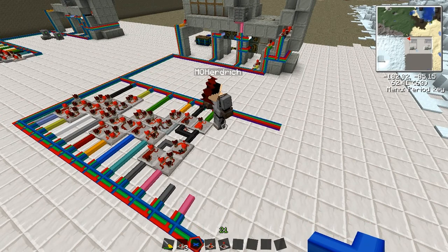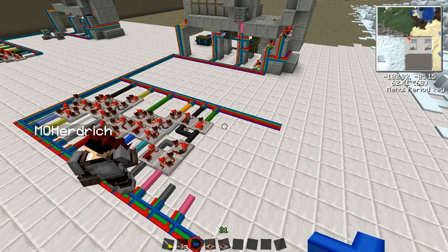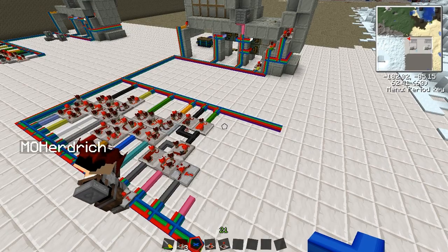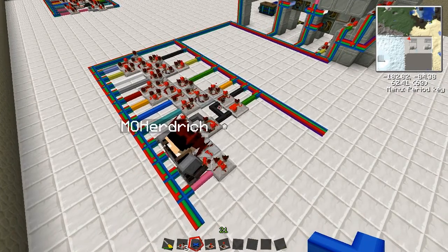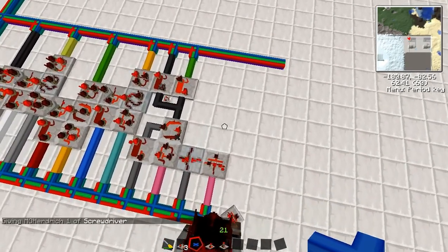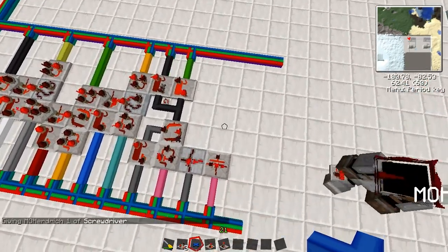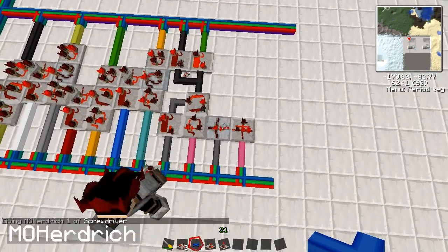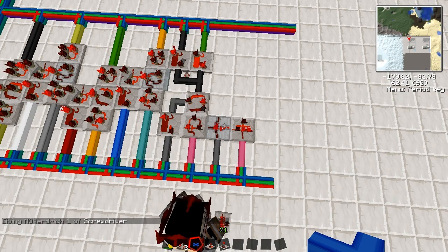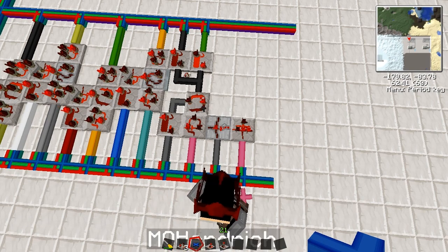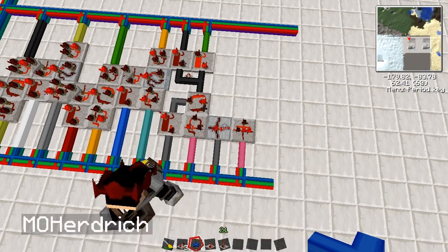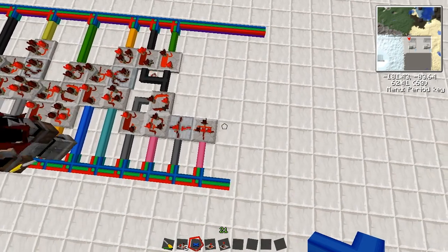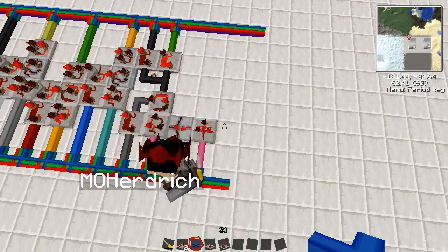Yeah, we just toggle the signal. Now we use a NOR to invert the is running output and feed it into an AND gate. Use a screwdriver. So basically we want to disable the input as soon as the door starts moving. So as long as the grey cable is disabled, we want the second input of our AND gate enabled. And when the door moves and the grey cable is enabled, we want the input for the AND gate disabled.